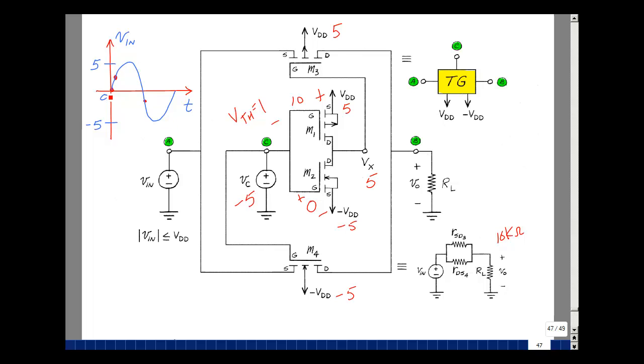Suppose that we have a slightly positive voltage here. So what is the source to gate voltage equal to? Well, it's roughly 0 minus 5, so roughly minus 5. Here we've got minus 5 minus 0. We've got also a minus 5 volts here. Less than threshold, less than threshold. These are very big resistors. Suppose they are, say, a gigaohm.